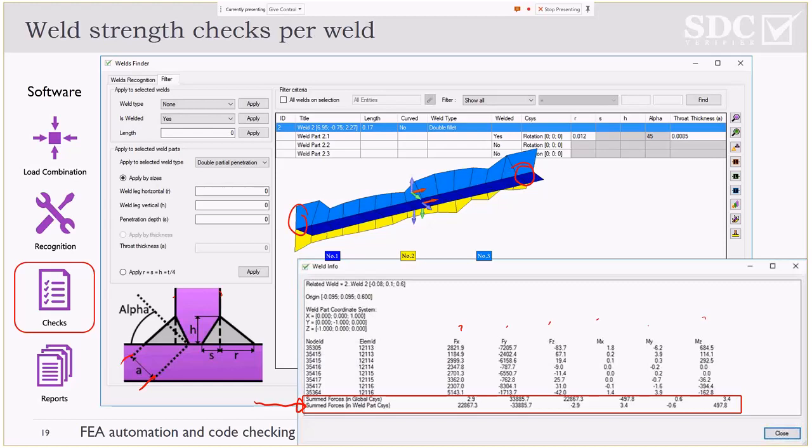With this method you can set detailed A heights for every weld, fairly simple and semi-automatically. So there is a very big saving in weld heights if you base your calculations on this model, compared to directly using the stresses for each element and trying to transfer that into some kind of A height by basing yourself only on equivalent stress at the edge.